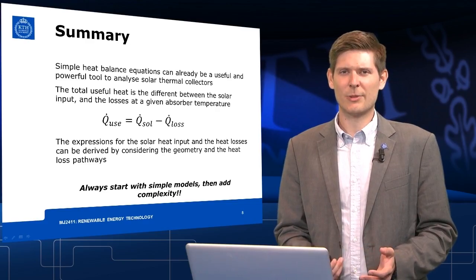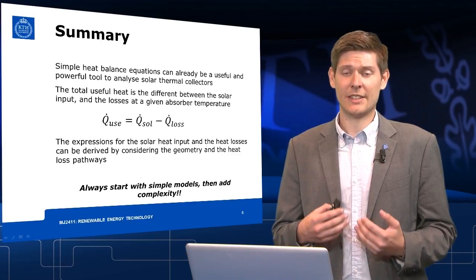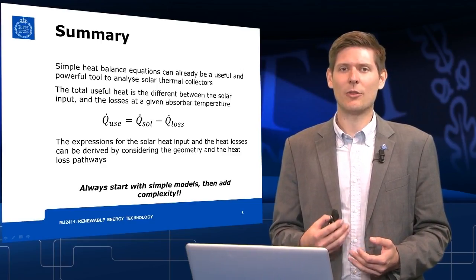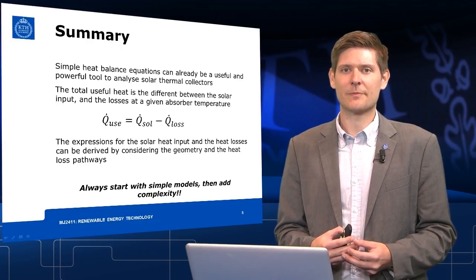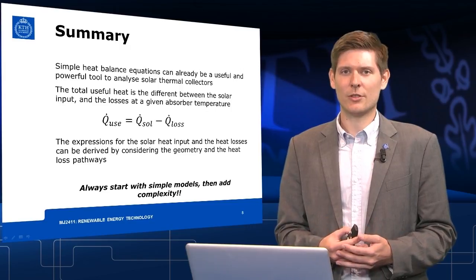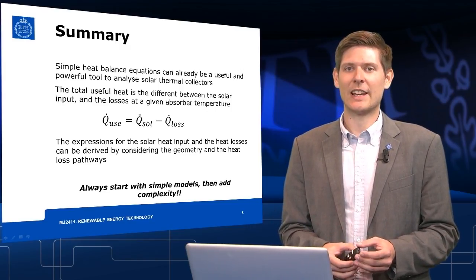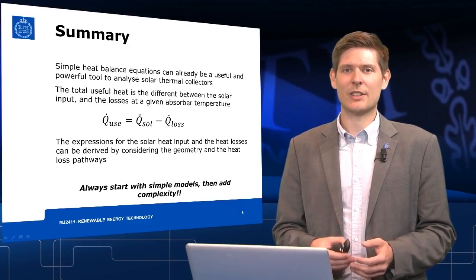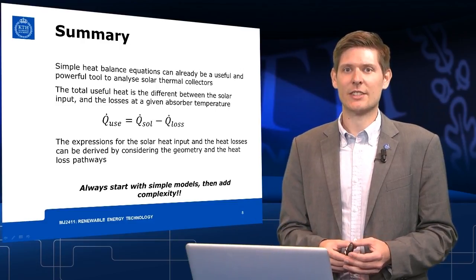In conclusion, we can say that by using a very simple heat balance, we already have a very useful and powerful tool to calculate solar power collectors. It is important also to point out that the usable heat which we get out of a solar collector is simply the difference between the solar heat input minus the heat losses.